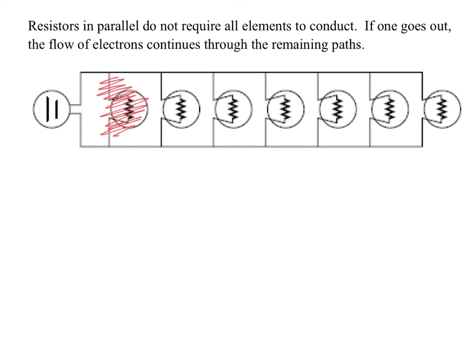There's a gap there, so this bulb would go out, and all the other bulbs might get brighter. Okay, and you'll see that in the lab today. You're going to see how that works. I think that's what happens to my lights, which is weird. Yeah, they may or may not get brighter depending on the way it's controlled. At home, it's different. You know, simple circuit you'll see today. Okay, but if one bulb goes out, they still remain lit in parallel. So this is what you have at home for the most part for any sort of lamp that has multiple bulbs in it. They're always in parallel. It wouldn't make sense to be in series. If you lose one bulb, you got to suddenly replace them all. Or you have to replace one before you can use any of the others.